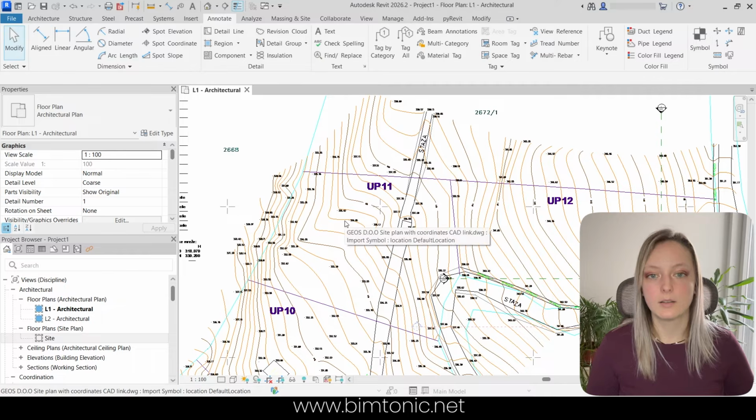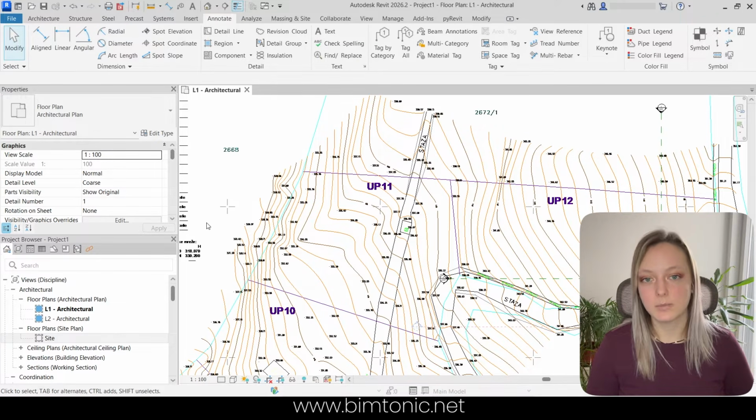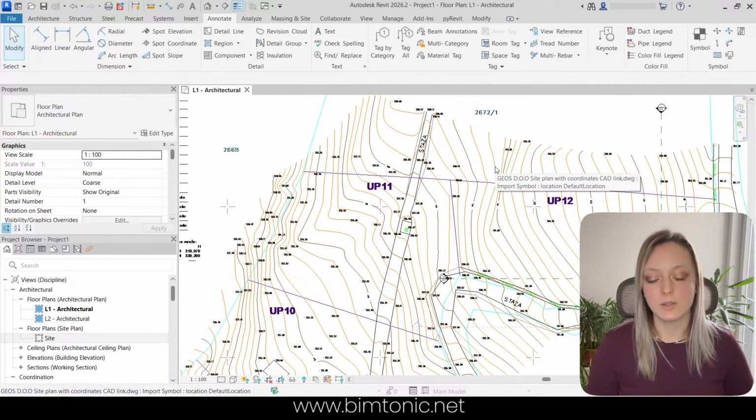This is the correct position of the true north, and that is the position of your file, of your plot and building in correlation to the world, basically. And this is the perfect setup for true north, but we actually have the project north, and project north is the setting, the placement of the building that we use in the floor plans. Basically, you do not wish to have this slanted plan in the floor plan. You actually want your plan to be with the straight lines.